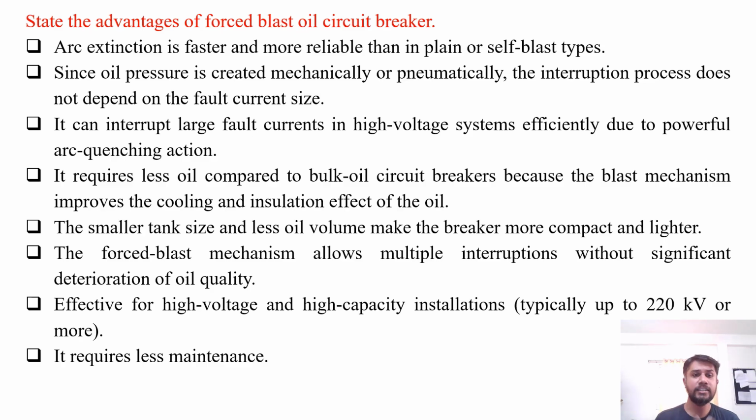It requires less oil compared to the bulk oil circuit breaker because the blast mechanism improves the cooling and insulation effect of the oil. The smaller tank size and less oil volume make the breaker more compact and lighter. The forced blast mechanism allows multiple interruptions without significant deterioration of the quality. Effective for high voltage and high capacity installations, generally about 220 kV or more. It requires less maintenance. So these are several advantages of forced blast oil circuit breaker.